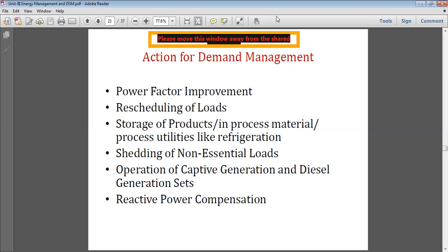We can switch off the residential feeder. If the residential feeder is switched off, there is no harm and no effect on the teaching-learning process. We can switch off the residential feeder for say 1.5 hours. So by switching off only one feeder, the maximum demand decreases. Once the maximum demand reaches the particular level which we have set, the residential feeder will switch on again.